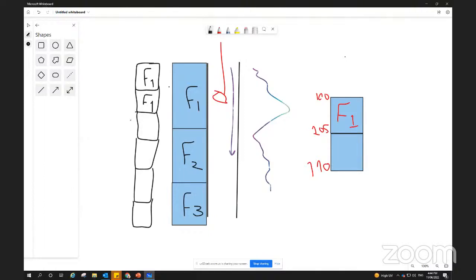So which facies to put? In the upscale process, you can define the way of upscaling, based on arithmetic value, the maximum value, the minimum value, or the most of approach. When you choose the most of approach, the software will see how much of this facies is occupying relative to the cell beside it, and how much space the second facies is occupying.